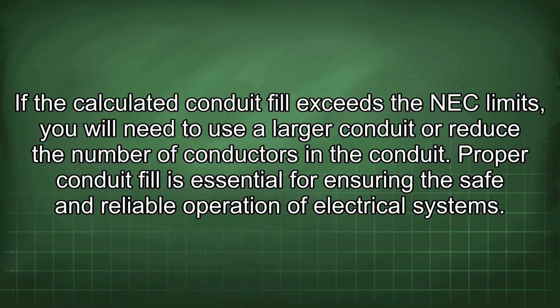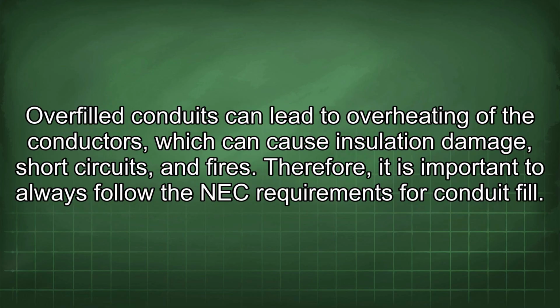If the calculated conduit fill exceeds the NEC limits, you will need to use a larger conduit or reduce the number of conductors in the conduit. Proper conduit fill is essential for ensuring the safe and reliable operation of electrical systems. Overfilled conduits can lead to overheating of the conductors, which can cause insulation damage, short circuits, and fires. Therefore, it is important to always follow the NEC requirements for conduit fill.